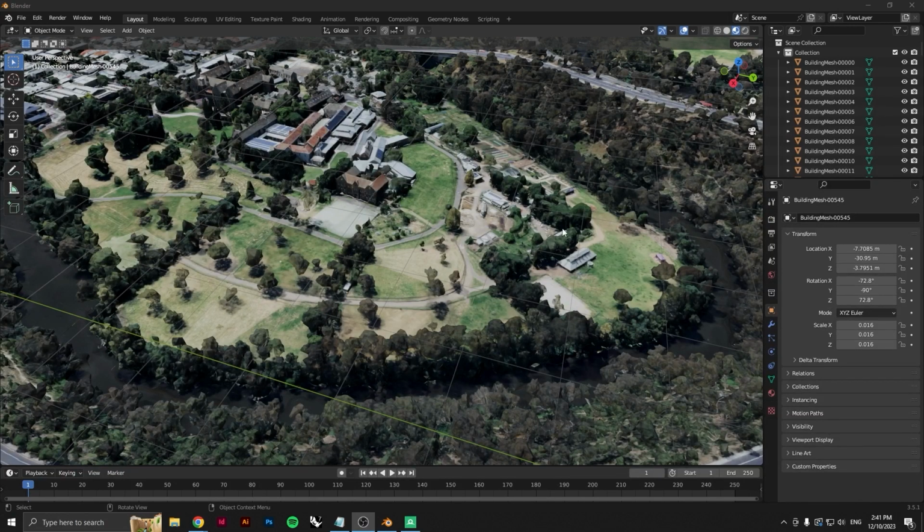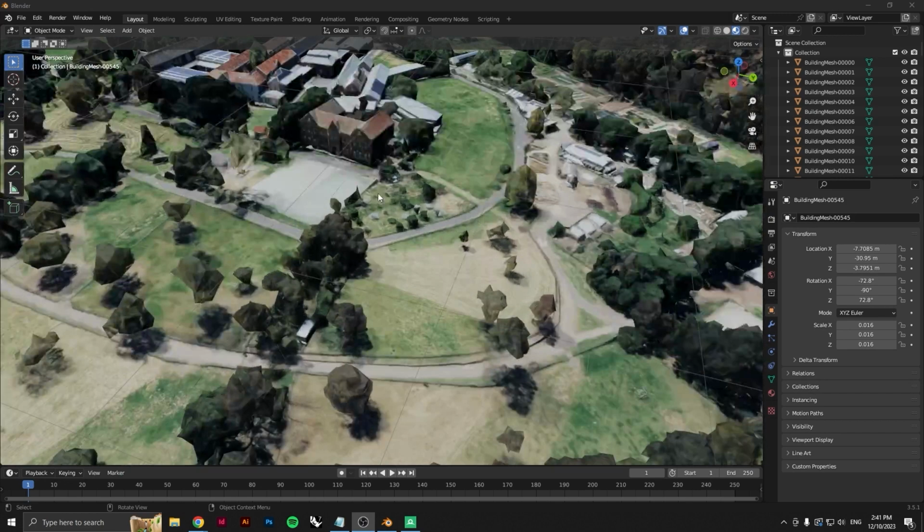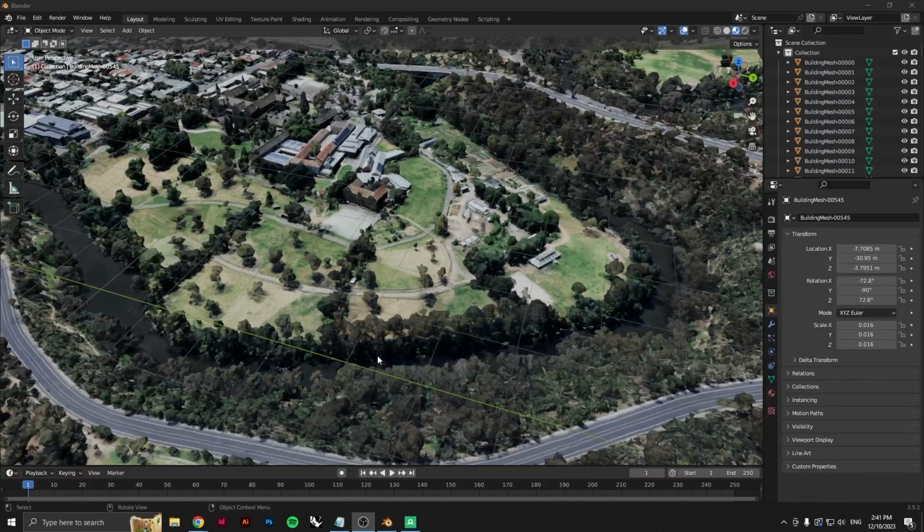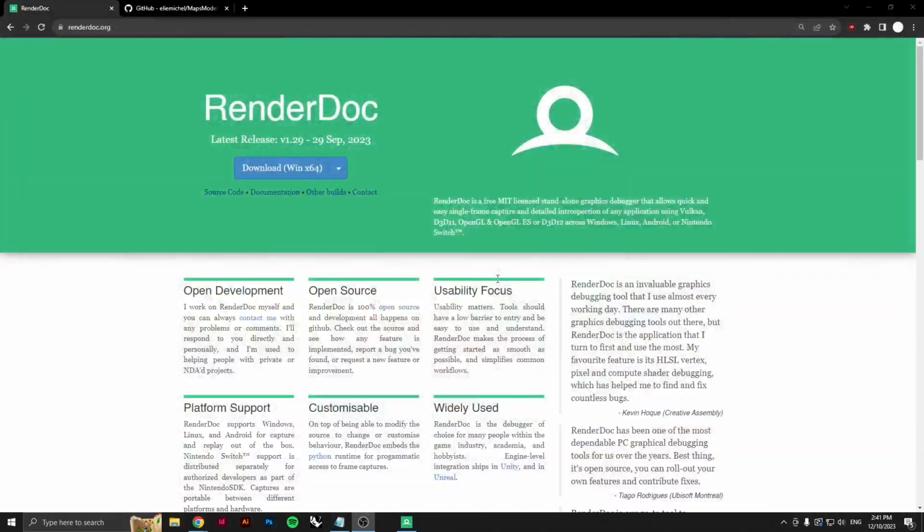I'm Angus. I'm going to show you how you get some of this high quality 3D Google Maps data and how you can import it into Blender. There's a couple methods for this. The first one I'm going to show is RenderDoc, and the other is a new plugin for Blender. That might be a second video, but this one will show the RenderDoc method, which is pretty fast. It's a little convoluted to get started, but I'll just close this and get right into it.